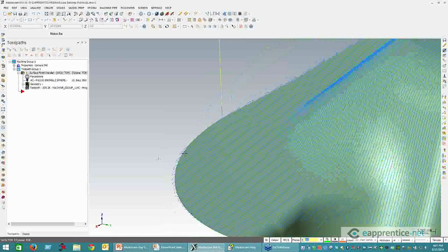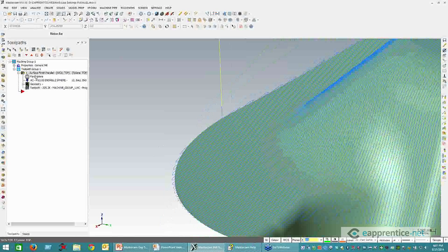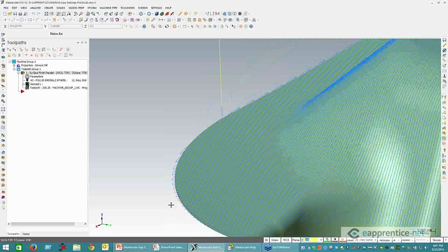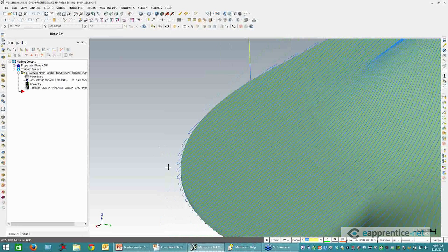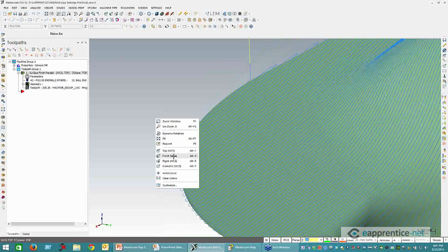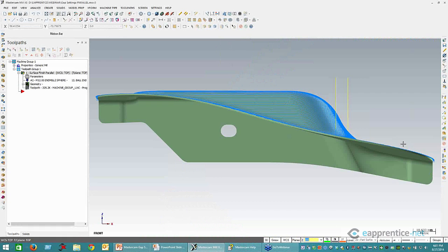I think that's part of it. This is all trying to give you the best of both worlds, allowing you to extend off of this. But this works really clean on a nice flat rectangular surface. When you've got a surface that is angled and curved in multiple directions, honestly you're kind of asking a lot from the software in some ways. So there are some times where the older legacy paths are more appropriate, and there are some times when those newer surface toolpaths are your better bet.